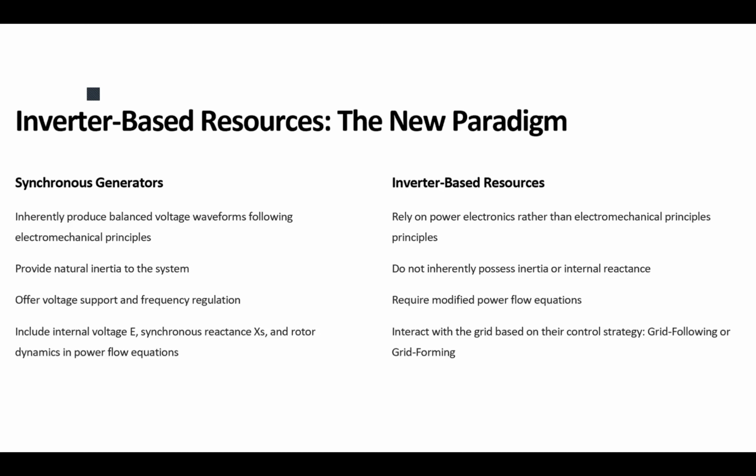We already talked about that: the voltage and reactive power are connected to each other. So if we can provide an adequate amount of reactive power in both directions, consumption or generation, that means we are able to stabilize the level of the voltage in our system. Inertia in the rotary machine would provide that.